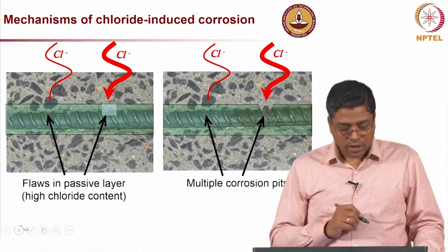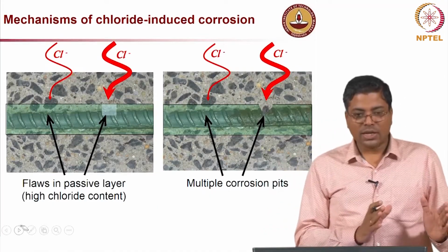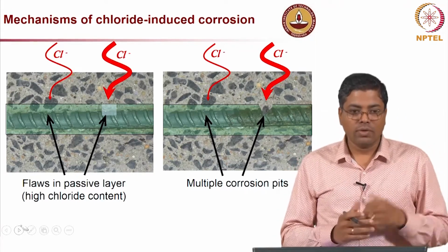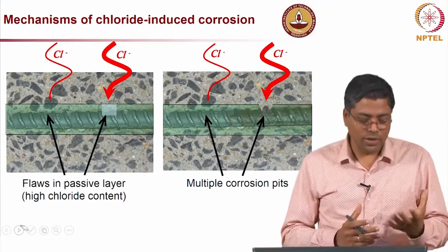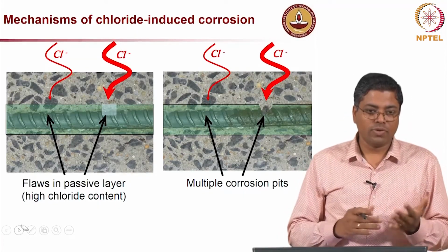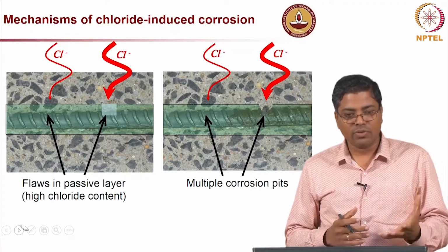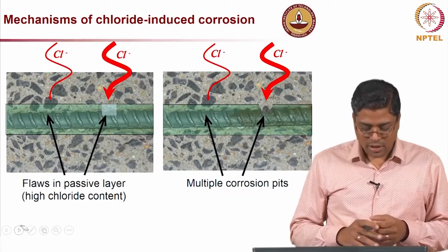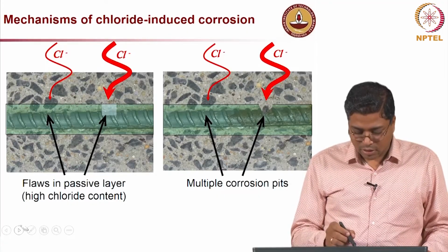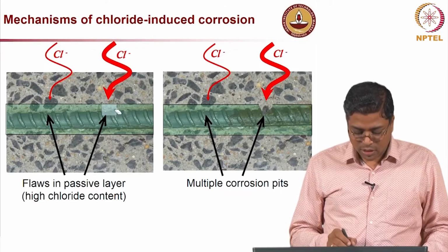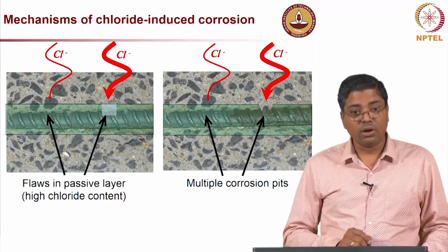Now, we looked at different types of structures and the reasons for where the source of chlorides is. We looked at marine conditions, airborne chlorides, or the materials used for making concrete itself. Whatever it may be, if the chlorides are reaching the steel surface, what you will notice is something called pitting corrosion.